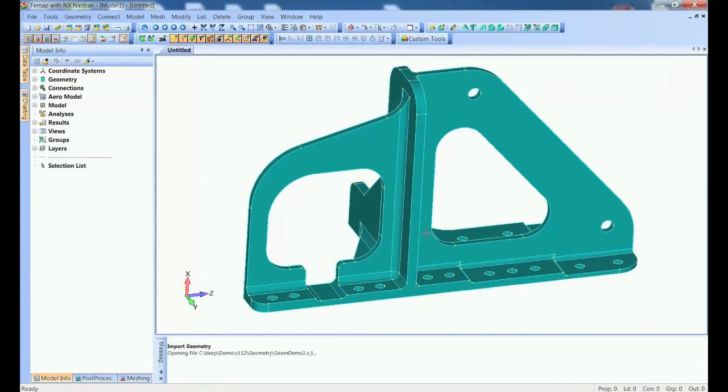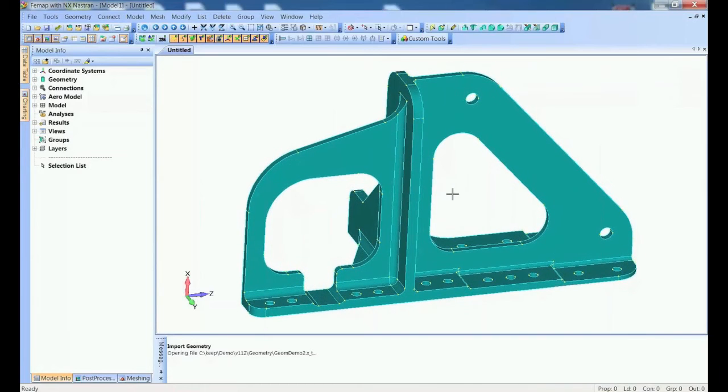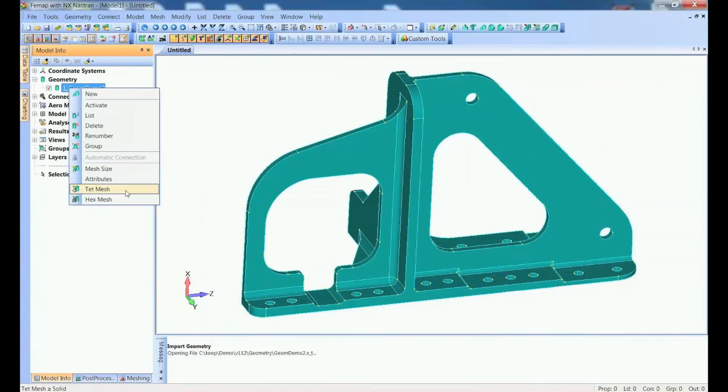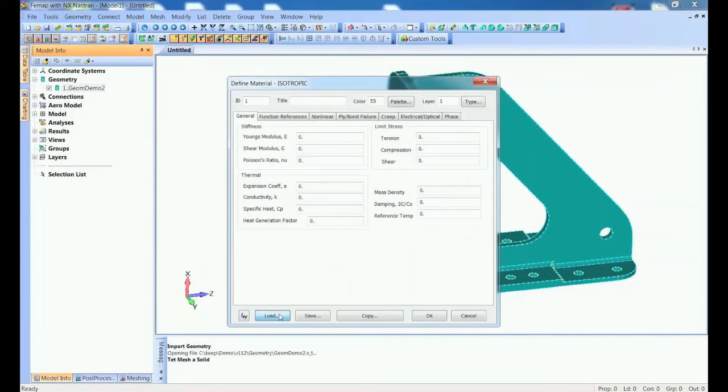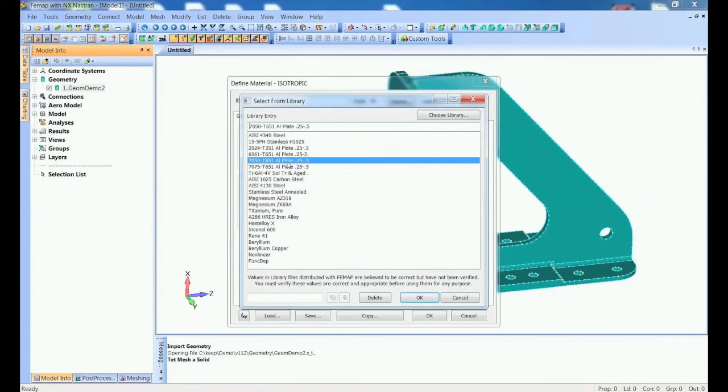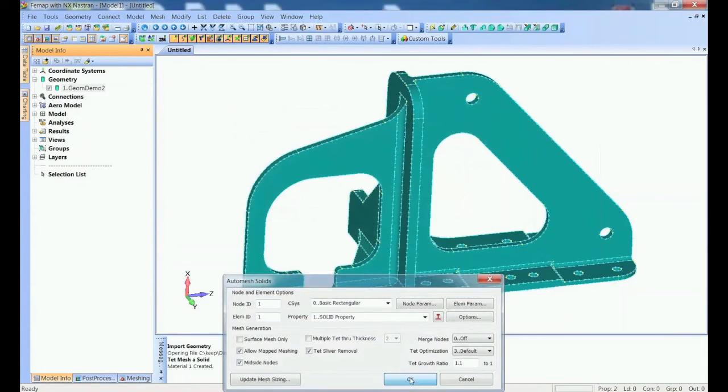So we're importing varying types of CAD data, whether from parts or assemblies. This will be the first thing you'll typically want to do. The role of FEMAP is usually the first time you bring in fairly complex assemblies of solids and idealize them into thin shell surfaces or beams, or you can actually leave them as solids. It's not that you can't quickly do meshes on solids. The problem is when you need to mesh a large assembly with complex surfaces, the model size will get huge if you mesh everything as a solid at one time.